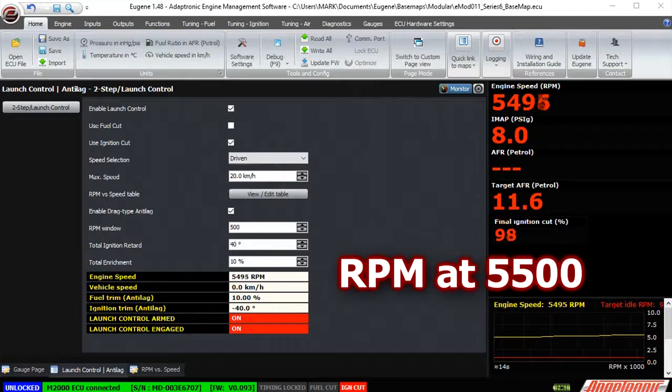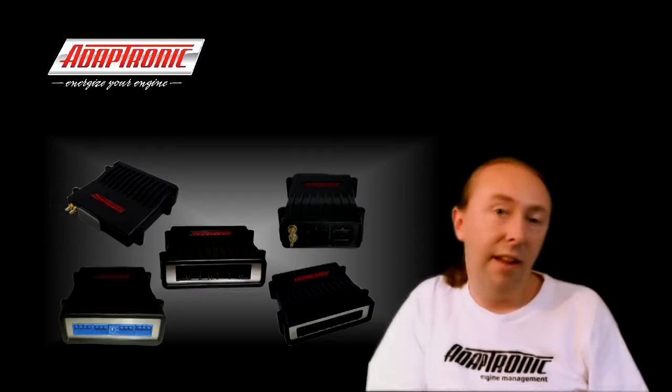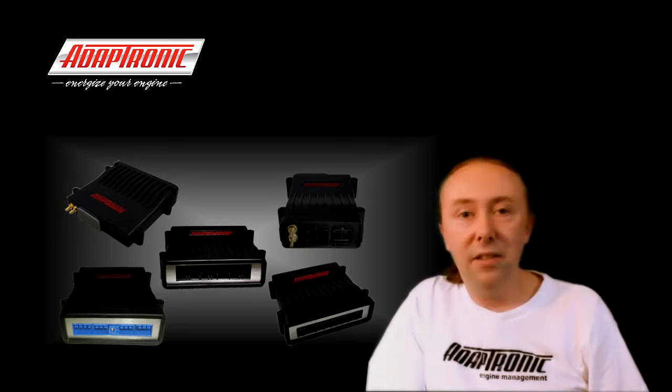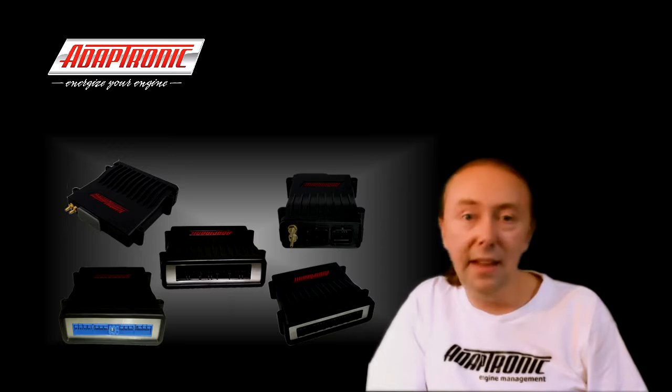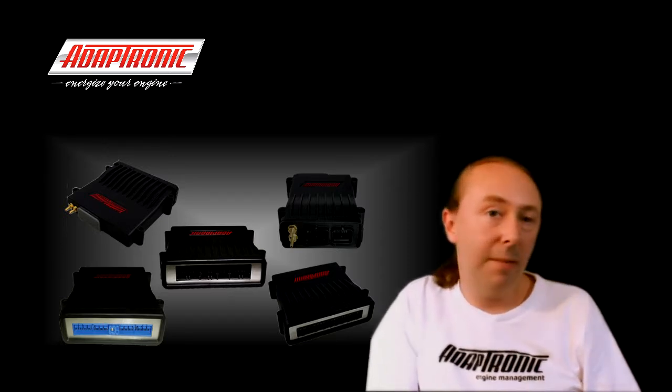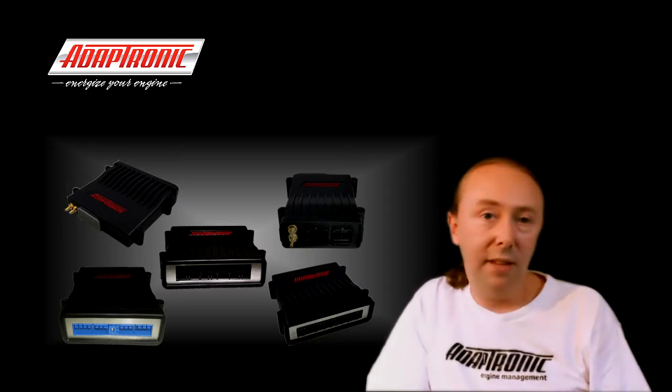So just like all the other functions, you can see all those variables: the amount of fuel and ignition cut that you have because of the launch control, and the amount of ignition retard and fuel enrichment that you have from the anti-lag. You can see them all live as it's happening. Also whether the conditions for launch control are met, and these are all saved in the log file as well.